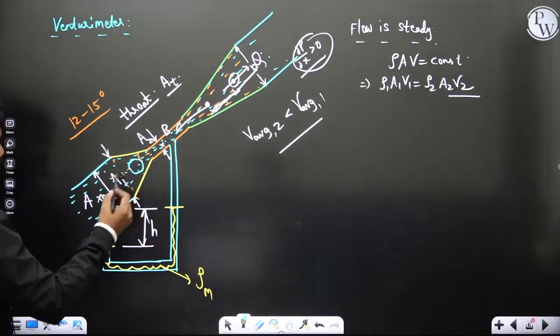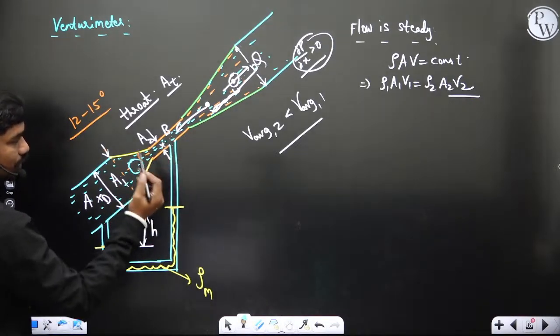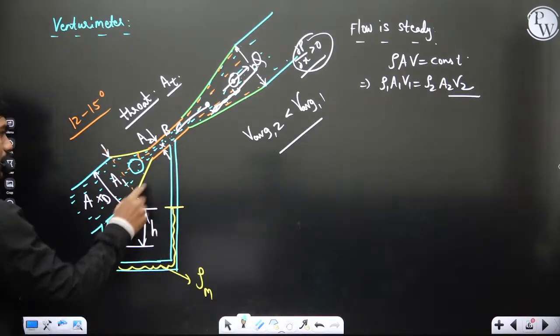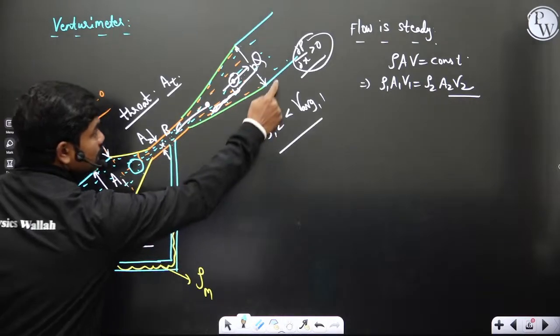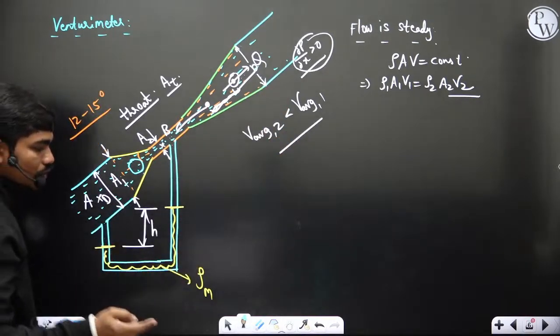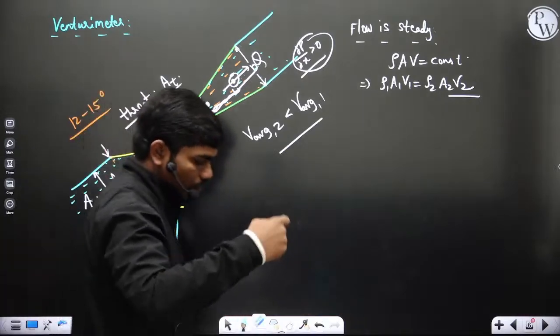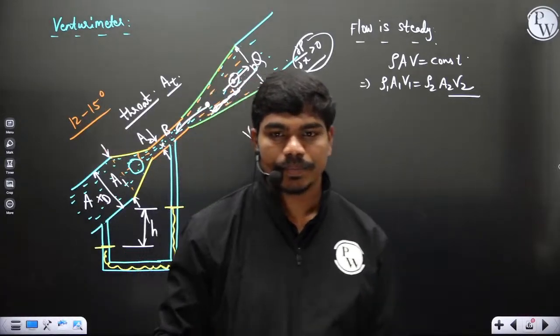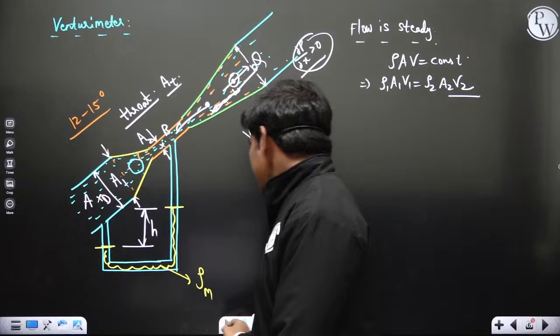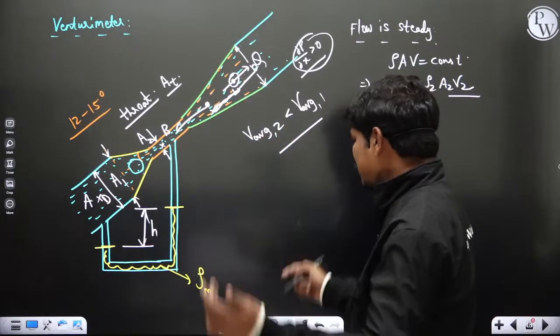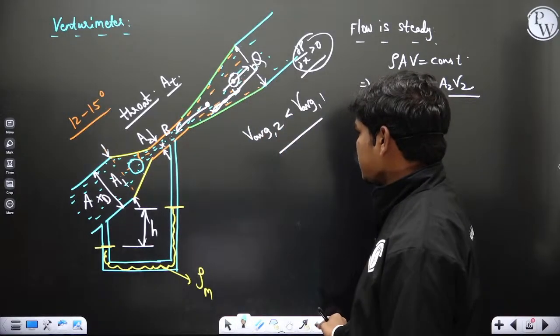So that's why we connect these 2 at locations where there is uniform flow. You can in fact connect this here and also this edge here, but you should connect only at the uniform flow points. That's why. Now if you apply Bernoulli's equation, then you can easily get into the things.